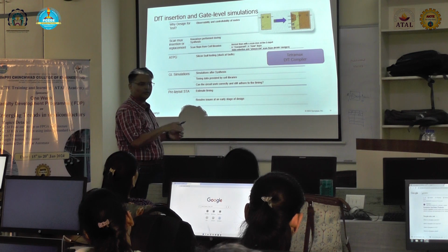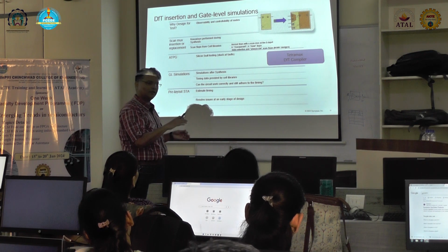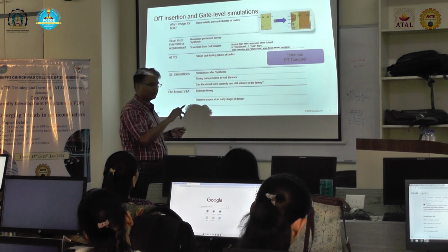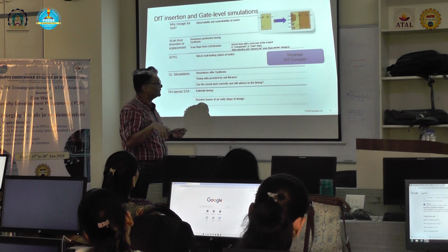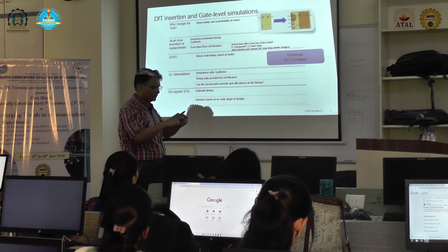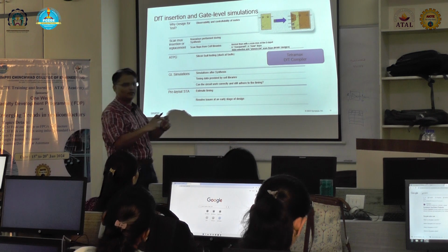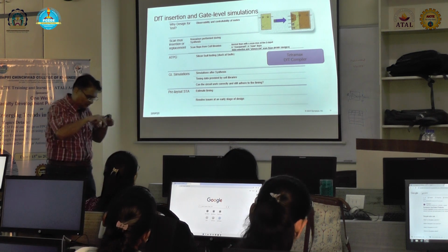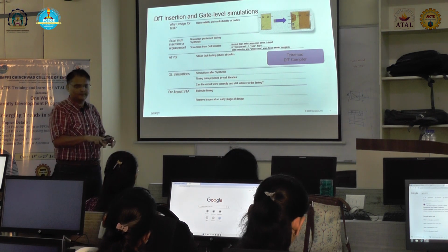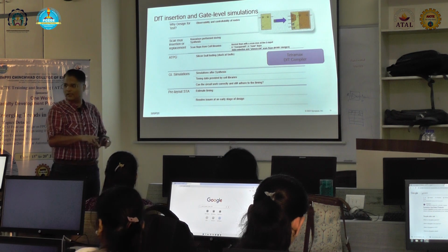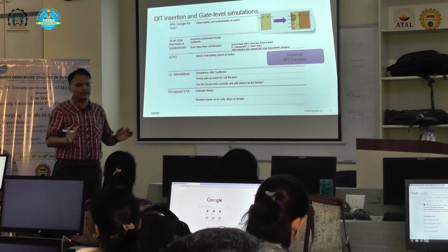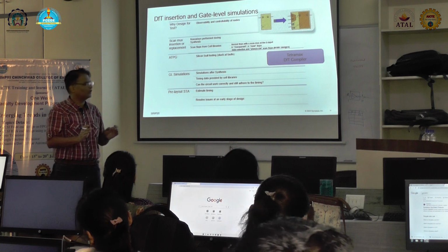So actually, we don't do the boundary scan ourselves. Boundary scan is normally done when you are placing the chip on the board. It is like a connectivity test, right?